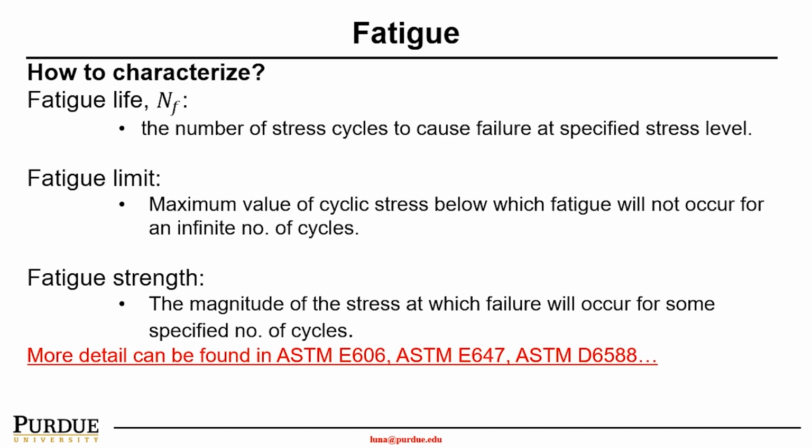So how to characterize fatigue? Let's quickly review the information you probably learned in some other classes before. Fatigue life, right, is determined by the number of stress cycles to cause failure at a specified stress level. Fatigue limit, right? The definition of the fatigue limit is the maximum value of the cyclical stress below which fatigue will not occur for an infinite number of cycles.